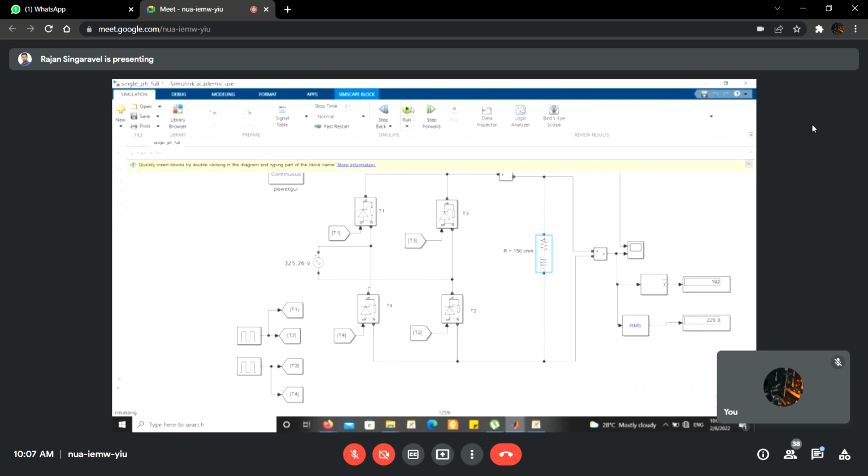Let us see how the waveforms and the average voltages are changing. After checking this value, we will go to the derivation. Our circuit is the same, firing scheme is the same, supply voltage is also the same, 230 volt RMS, but apart from the 150 ohm resistor load, an inductive value of 40 millihenry is added.